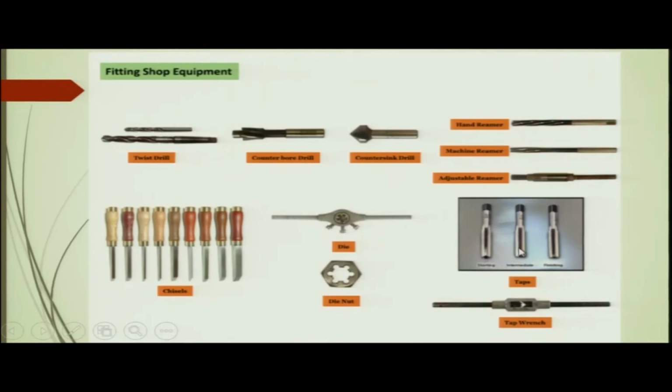A little more material will be removed, but it is still not the final thread, not with the complete surface finish which is required. For that you need the finishing tap. How these three taps are used in different ways, we will demonstrate in the lab, and you will see how the holes can be tapped, that means how the internal thread can be made with the help of the taps.